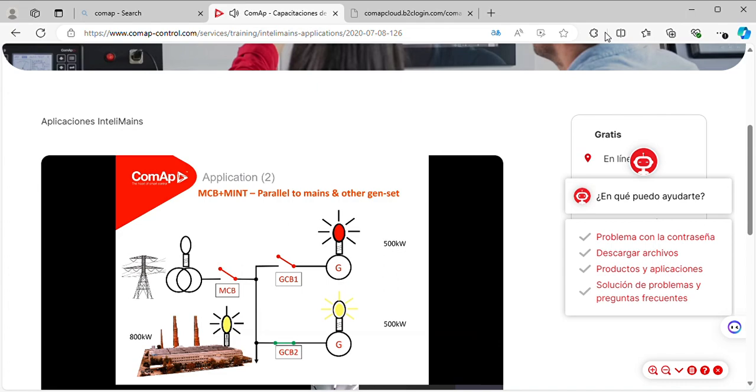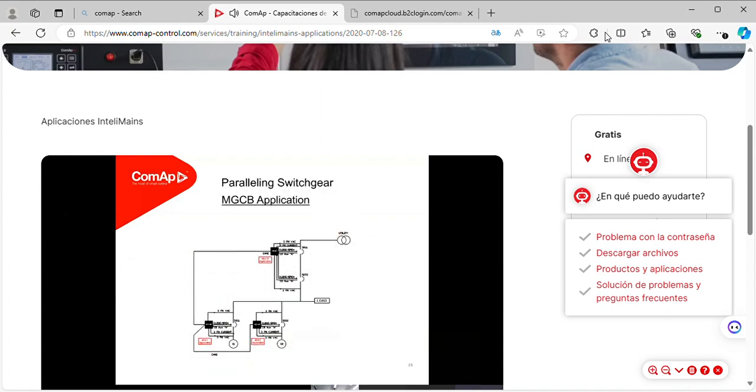And this is pretty common, and at times there are operators just to trip a certain amount of load after the grid failure happens so that my current genset capacity can take care of the load. Now, until the grid returns, I cannot feed the total load on the system. So once the grid returns, it goes back to normal. To overcome this, either we need to upsize the gensets or we can look for another solution, which we call the MGCB application, Master Generator Circuit Breaker application.